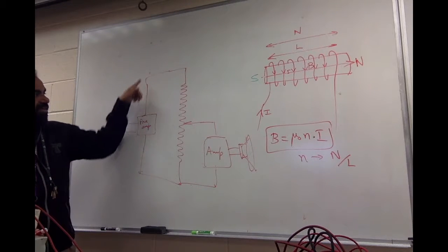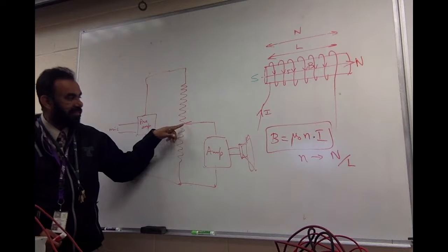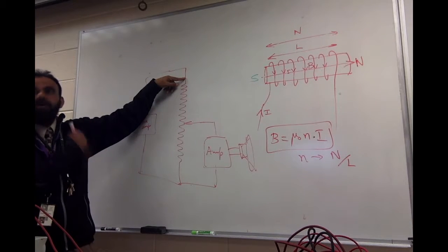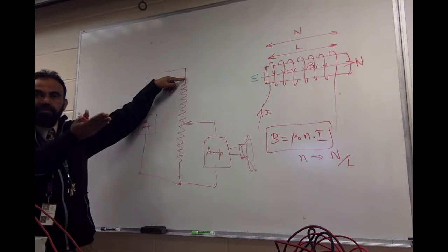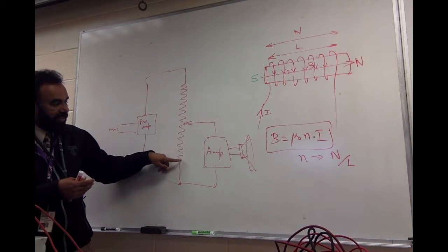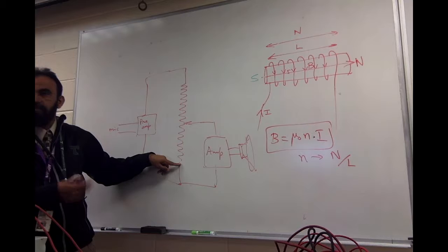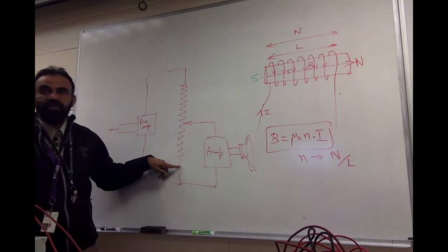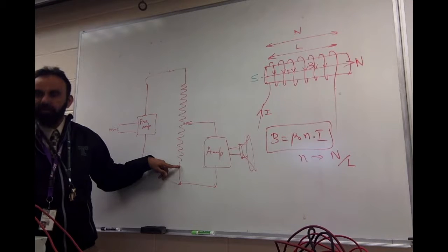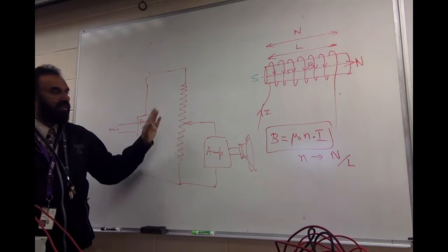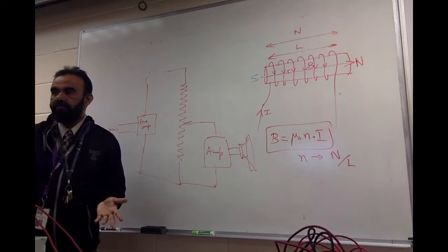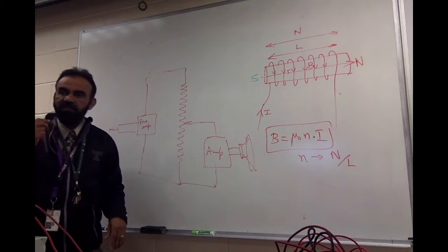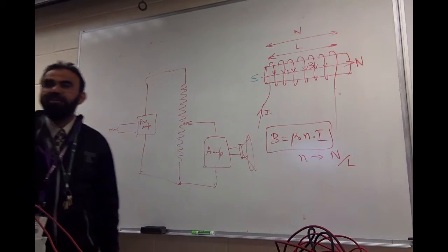So whatever signal is coming out from the preamplifier, if I connect this all the way up here, the amplifier will get all of the signal, and therefore it will be loud. And if I drag it downward here, what's happening? When I drag this down, what is the signal coming to the amplifier? Nothing, and therefore it will be 0. So basically it's like a volume control. You control things with this. Just a potentiometer like this will be able to do all the controls.